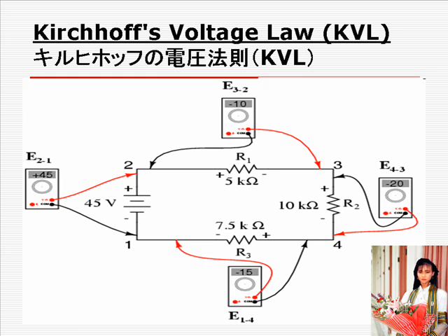However, for this lesson the polarity of the voltage reading is very important. When a voltage is specified with a double subscript, the characters 21 in the notation E21, it means the voltage at the first point 2 as measured in reference to the second point 1. A voltage specified as E_CD would mean the voltage as indicated by a digital meter, with the red test lead on point C and the black test lead on point D. The voltage at C in reference to D.